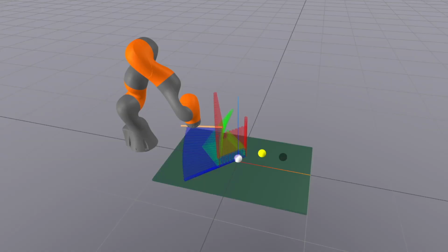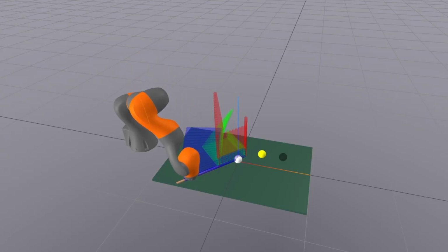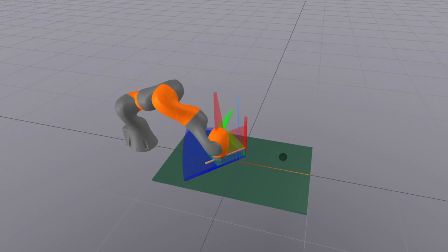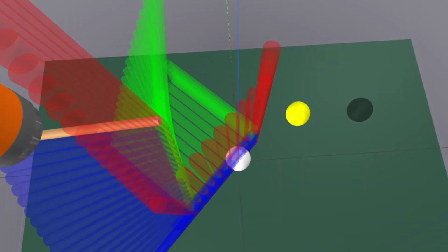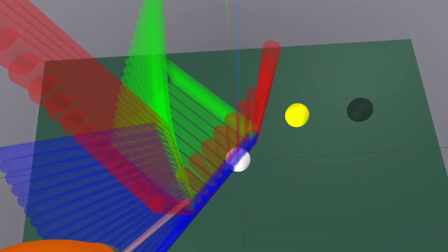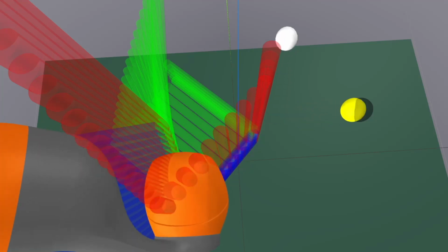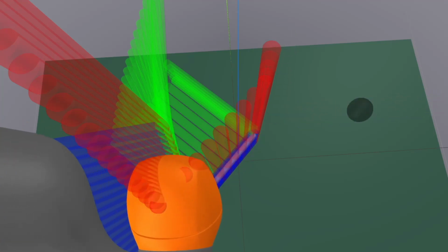The goal position of each state is used as an endpoint in interpolation. We set the number of keyframes and amount of time between each pair of endpoints. We determine the rigid transforms of the cue tip for each endpoint with respect to the world frame, and interpolate between them using Drake's piecewise polynomial first-order hold and piecewise quaternion slerp.